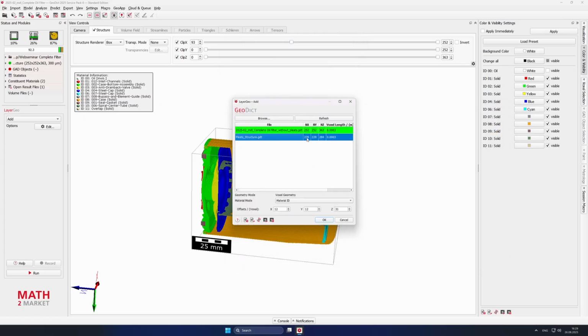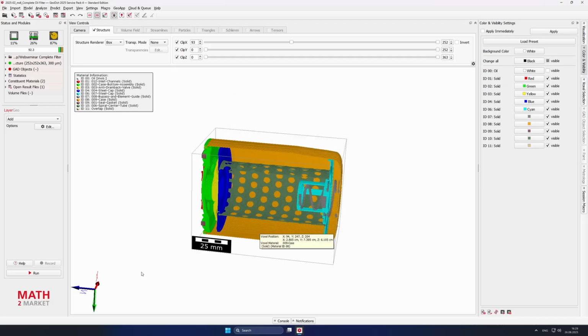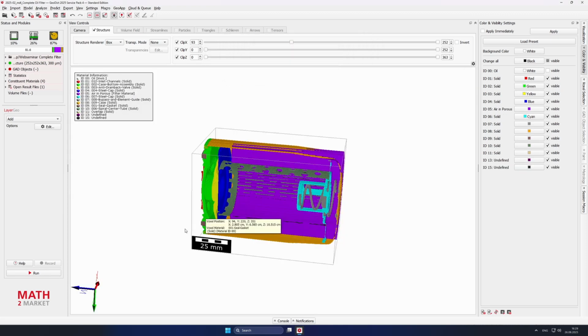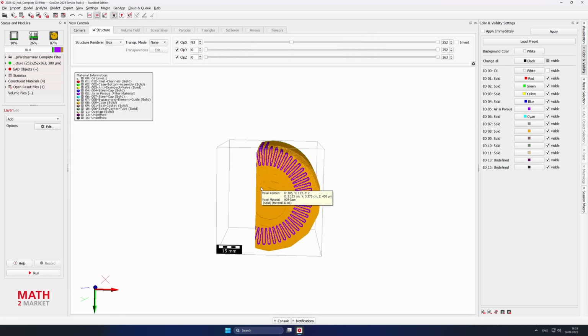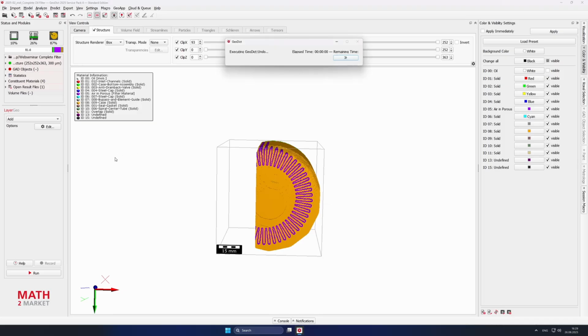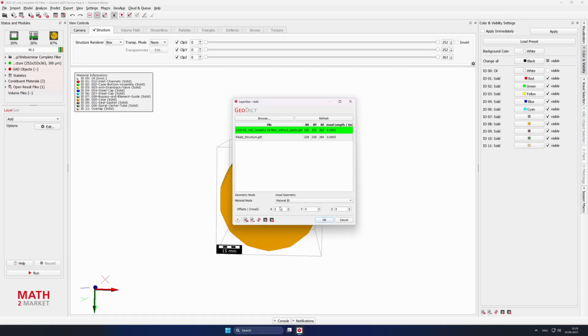And as you can see here, those values for nx and ny are not matching. If we just typed in an offset of 0 in there, then the pleats would be on the left side, which is not correct. I will just show it directly to you if we just import them without an offset. And as you can see, then we have the pleats in there, but we definitely need an offset. Then we will just undo that and go for an offset itself.